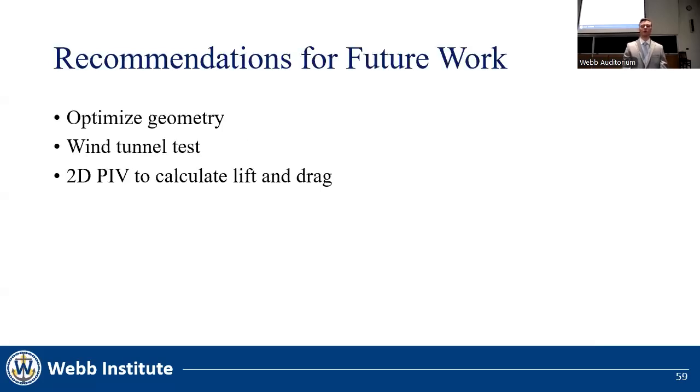To further study the effects of wavy leading edge rudders, there are a few steps that could be taken. The first recommendation for future work involves varying the wavelength and amplitude of the wave used to create the wavy leading edge in order to find an optimal combination. Now that the wind tunnel is operational, tests could be conducted in the wind tunnel to measure lift and drag. Finally, purely 2D PIV could be conducted with the camera located directly below the foil. This perspective could lend itself to better use of DiNapoli and Ng's MATLAB program. It could then be used to calculate lift and drag based on the PIV data.